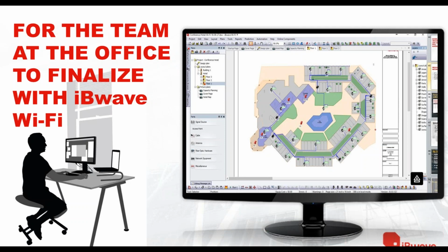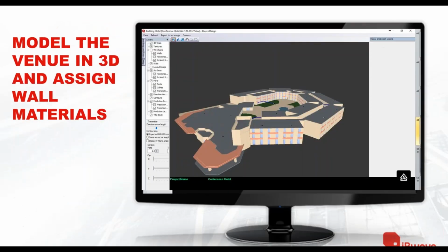So I'm just going to run through some of the key features of the PC version. So we opened up the hotel design that we got from the site survey, and one of the things you can do is model the venue in 3D and start to assign your wall materials. So you can import the floor plan using your AutoCAD file. You can do this with any image file, or you can do this with a PDF, and you can model your venue in 3D.